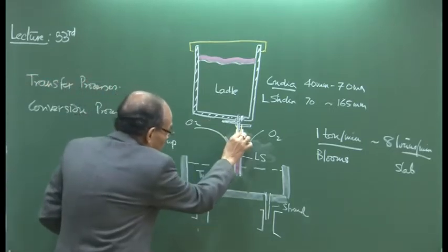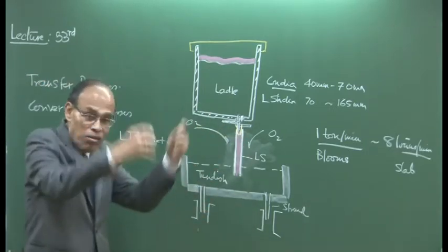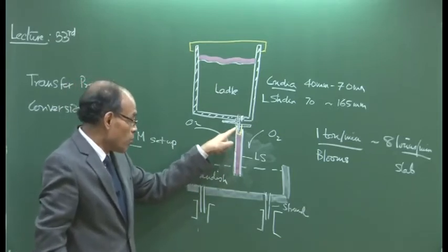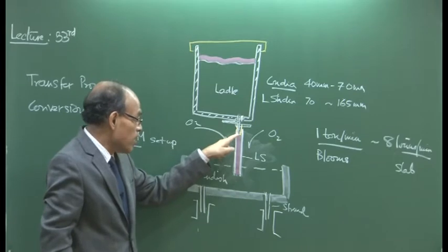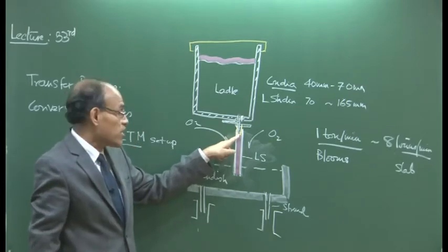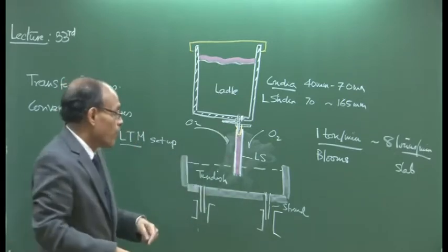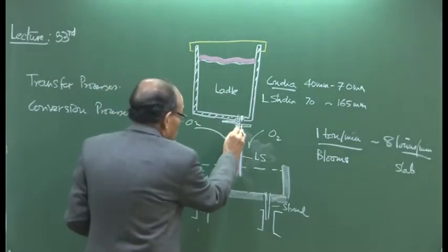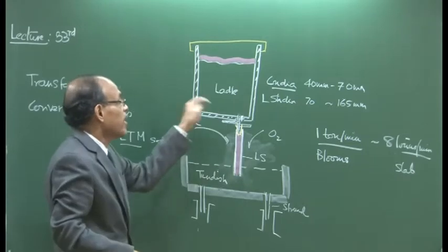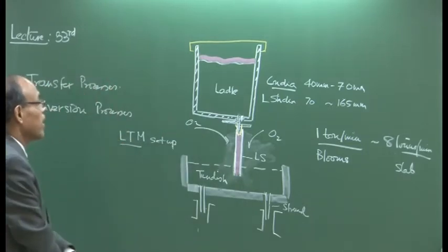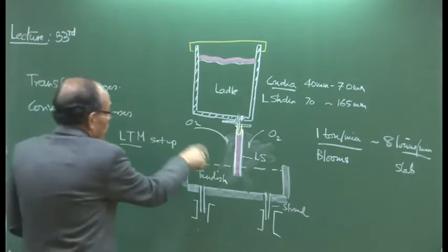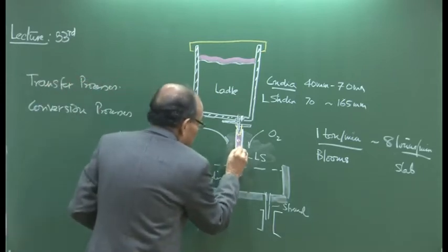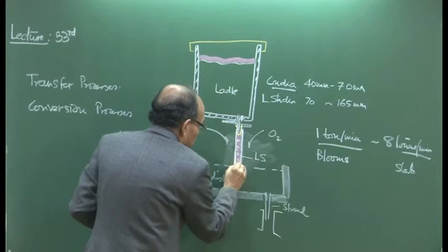When molten metal comes out, locally in this region which is exposed to the atmosphere through the leakages, low pressure regions thus created will draw air in. The pressure here is low because of the flowing fluid, so if there is a leakage here, the air will automatically get sucked in from that environment, and that will lead to a scenario where we can have bubbles of air distributed.